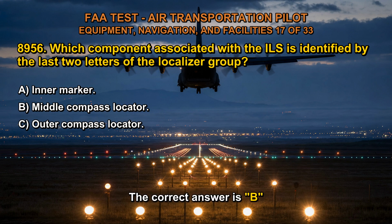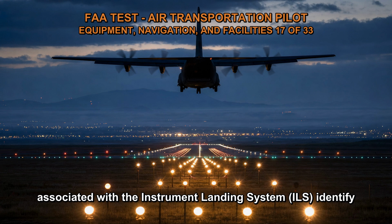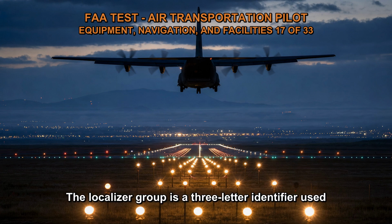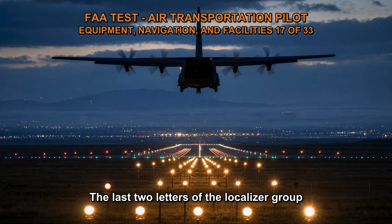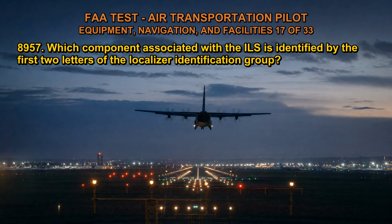The correct answer is B. The last 2 letters of the localizer group associated with the instrument landing system, ILS, identify the middle compass locator. The localizer group is a 3-letter identifier used to designate the specific ILS installation at an airport. The last 2 letters of the localizer group typically correspond to the middle compass locator.